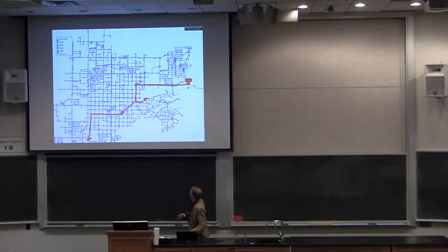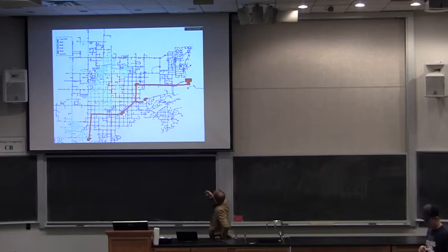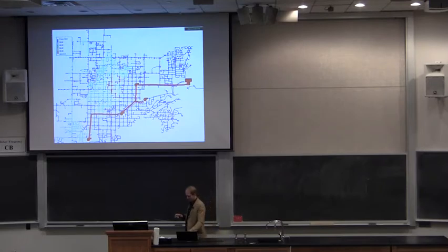So again, we did some hydraulic modeling, and what we showed them is that, again, we're tracing a well. This well was called to turn on when the tank got to a certain level, and we put some Kool-Aid in the model to see where the water was going. And 100%, even though the water was being called by the tank, they just assumed, well, the tank was filling up because the pump turned on. But 100% of that water was going down in their system, not going up. And this is the pipeline that they thought was out of capacity. They needed a new transmission line, and they weren't keeping up, so they thought they needed a new well.